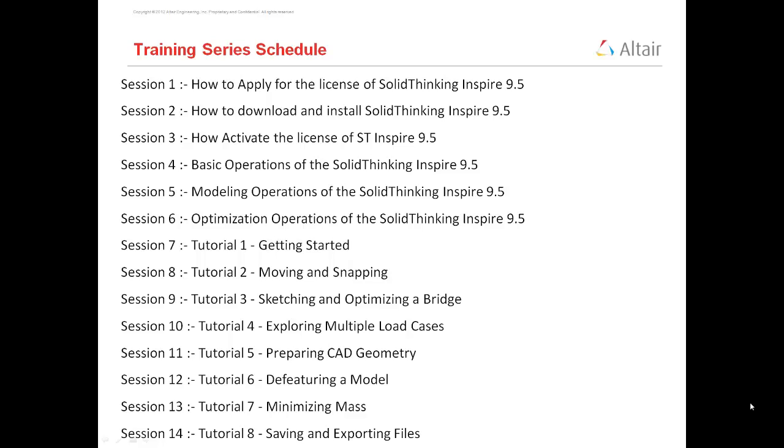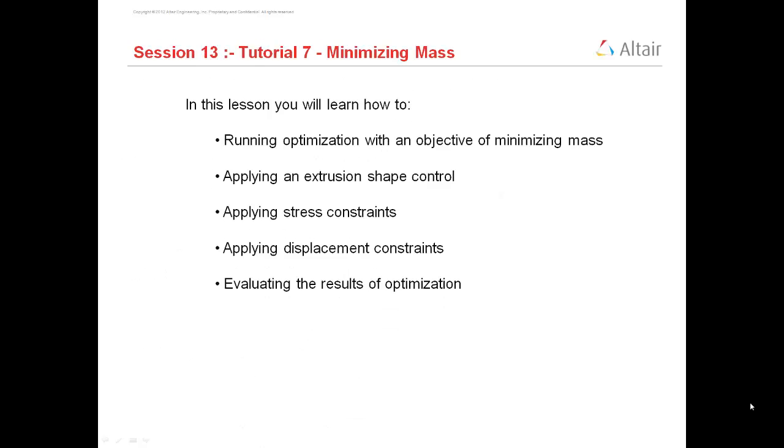Now in today's session, session number 13, I am going to discuss minimizing a mass load case, how to solve that tutorial. And then in the last session, I am going to discuss saving and exporting files. So today we are going to see running an optimization with an objective of minimizing mass, then applying an extrusion shape control, then applying stress constraints, applying displacement constraints, and evaluating the results of optimization.